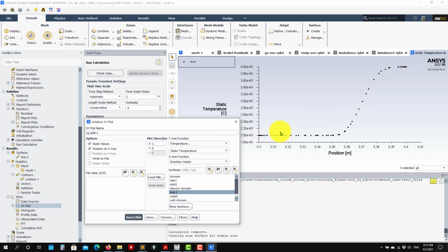As you put temperature, you will see the hot and cold. So in this case, this should be a very sharp interface, but we have a diffusion coefficient also. See that it diffused a little bit. But in the next case that I will show you, a passive scalar, we're going to put the diffusion coefficient of that passive scalar equal to 0. So this should be a discontinuity, like a shock wave, a sudden change. But due to the mesh numerical considerations, there is a little bit of diffusion.